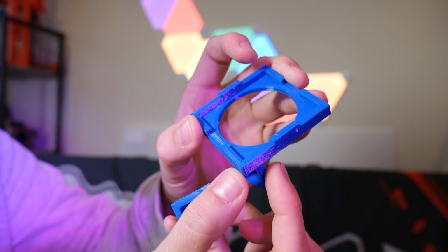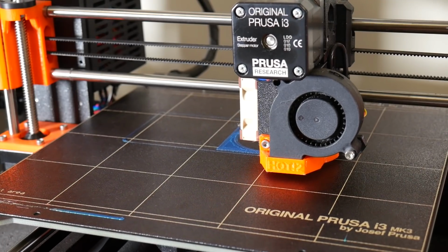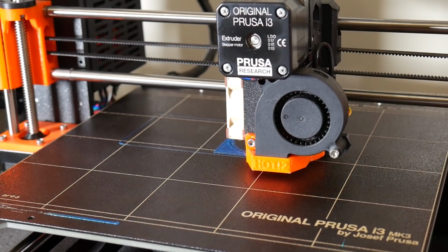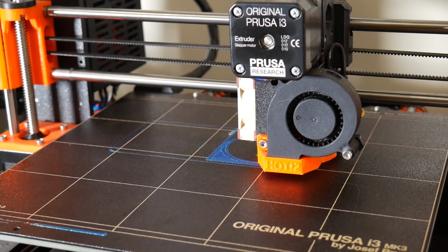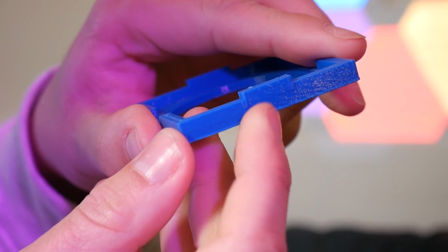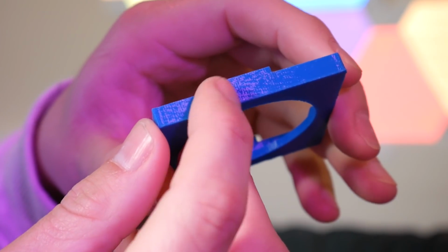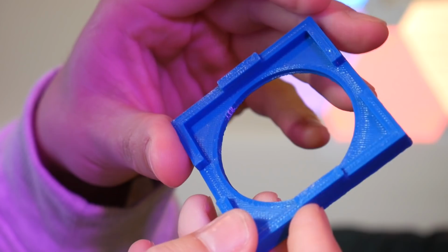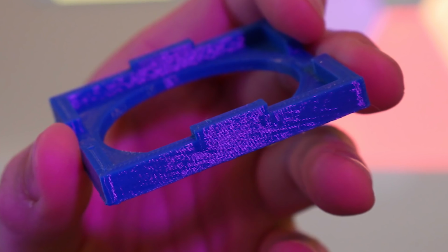And the elephant foot compensation did work okay, but it turns out my first layer was just really quite close on my Prusa Mk3, to be safer than sorry. And there is still a tiny bulge there. Not as bad as it would have been if the elephant foot compensation wasn't used, but I think with this setting, I would like to see it be able to be used for more than the first layer. Maybe the first 2 or 3 layers, you can compensate by a little bit.